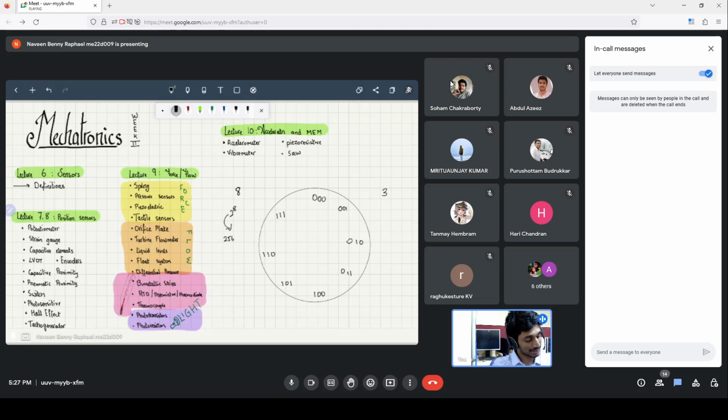So this will be the thing in binary digits. Now, one small issue with binary digits is that as you change from one value to the other, here there's no issue. We are going from 0 to 1 and only one bit is changing. That's perfectly fine. But say you're going from 0 to here. Now 3 bits are changing. That is, this 0 is becoming a 1, this 0 is becoming a 1, and this 0 is also becoming a 1. This might seem like a small issue.